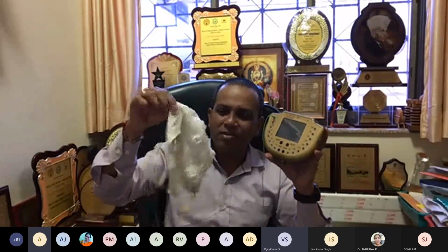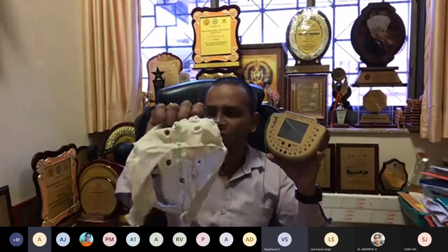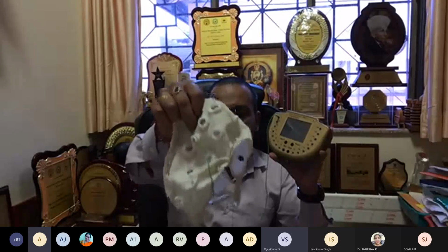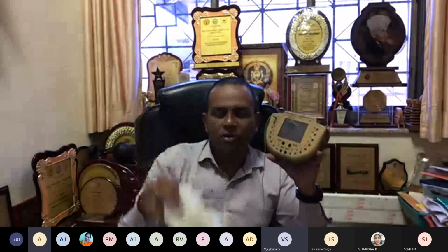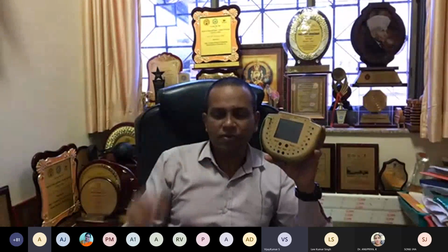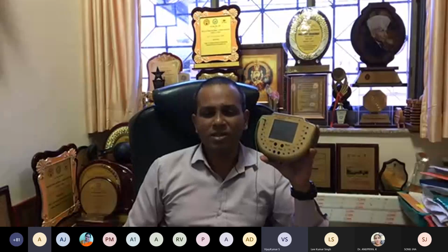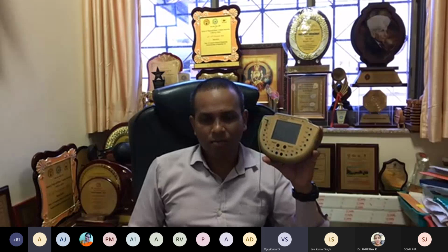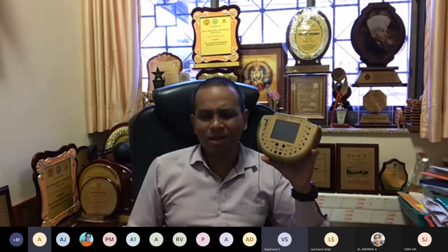Similarly, the ground and reference also you have to connect to the EEG cap. Ground you can connect anywhere. Reference you try to connect to the same lobe where you are taking from. For example, I am taking from this particular lobe, and I have already connected one channel. So you can take from the same EEG cap, the same lobe, so that you have the reference of the same type of channel. This is to avoid any impulses or artifacts which sometimes record an unusually bad signal because of some external noise.